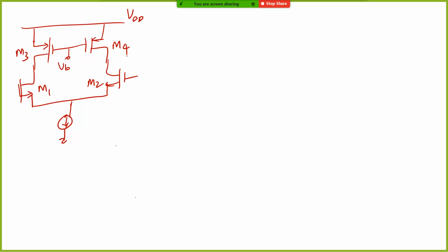Now what is this circuit basically? Common source with what type of load? It is not an active current source, it's basically a current source load. So the half circuit will basically look like this, right?